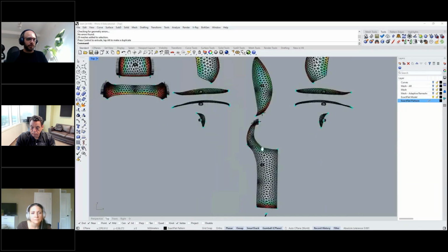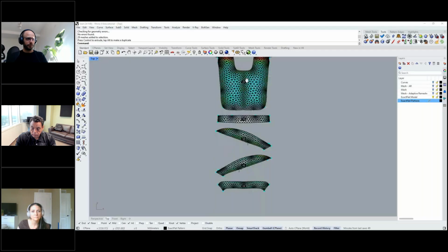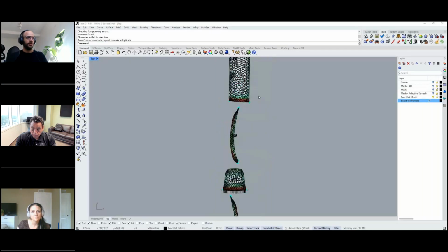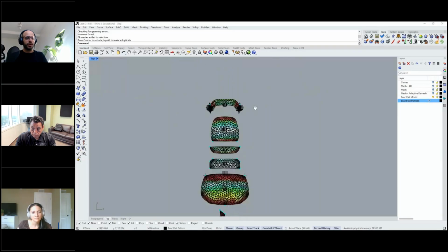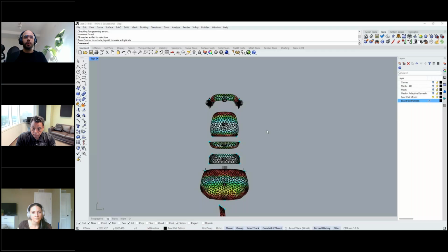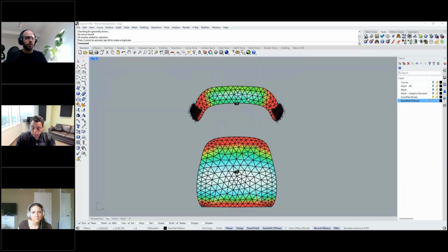What I mean by preview is that right now, at this very first stage of the flattening process, we are taking our pieces and dropping them on the ground or on the table. These are just very raw projections of the patterns that we want to create. So at this current stage, since they are being dropped on the ground or on the table, our patterns will have folds or wrinkles, and we'll want to remove these folds or wrinkles by extending those meshes on the ground.